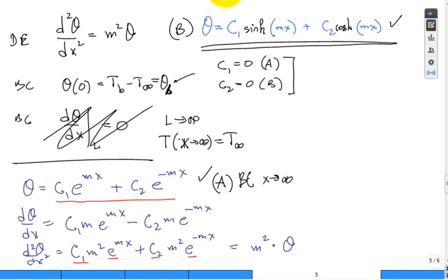So we apply this boundary condition. I'm going to make it in color. So theta b, that's the theta at x equal to 0, is equal to C1 times the sinh of m times 0. What's m times 0? 0. What's the sinh of 0? 0. C1 can be anything. This equation will work. Plus C2 times the cosh of m times 0. M times 0 is 0. The cosh of 0 is 1. Guess what C2 must be for...